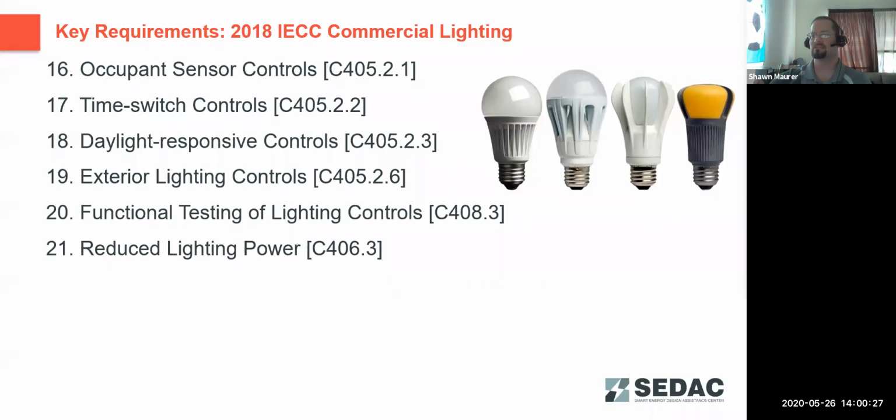And we've had that question come in a couple of times recently, like-for-like equipment replacements. They do have to be properly sized to the building's loads as best as they can be determined. And similarly, with those, the new unit may also need to have such things as the economizer or the economizer controls and the like.